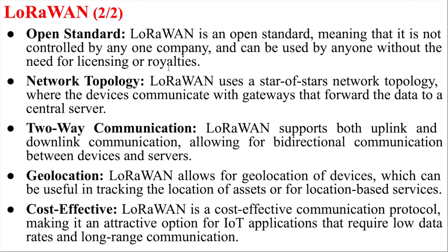And this is an open standard. That means it is not controlled by any company. You can modify the protocol based on your requirement. It supports star of stars topology, where all devices are connected with the gateway. That means they also support one-hop communication. All devices can directly communicate with the gateway, and they support two-way communication. A device can communicate to the gateway, and the gateway can also communicate to the device, not only one-way communication. Geolocation, that means they also support geolocation, at which device, where is its location, and what it is working on.